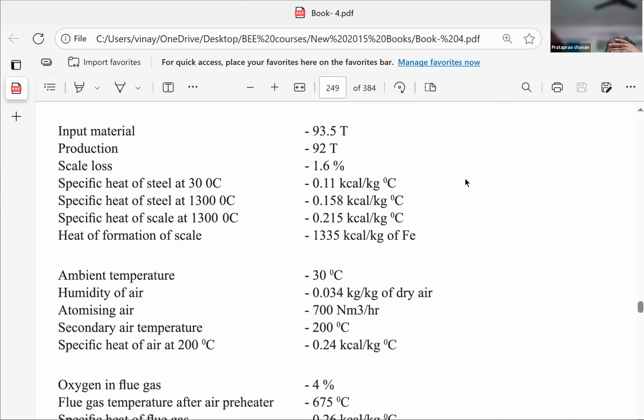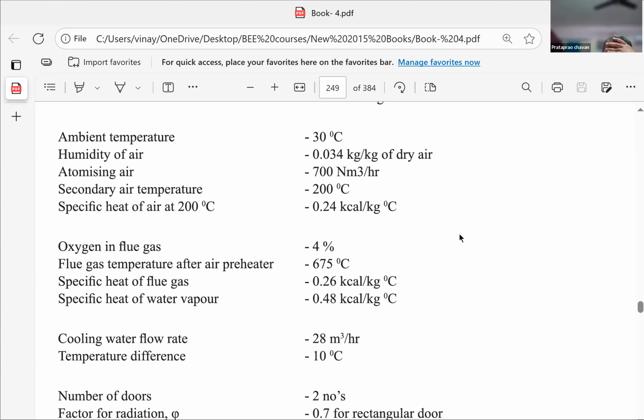It is the heat loss in scale, heat loss going into the metal, heat loss going into the air, heat loss going into the exhaust gas, where you need three parameters, m, Cp, delta T, and all your heat calculations are correct. Now, one thing again I would like to remind: when you do any calculations, you write the formula first. It is always better. Write mCp delta T and then put in the values corresponding to that parameter.